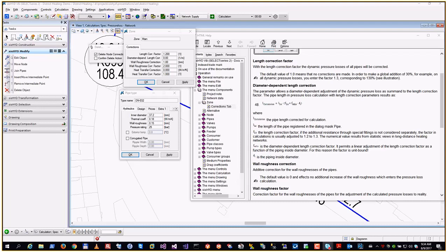And the reason behind it is that, maybe you can write a formula again. One of the most important formulas is that the heat load is the mass flow times the heat capacity times the delta T, the temperature difference between supply and return.